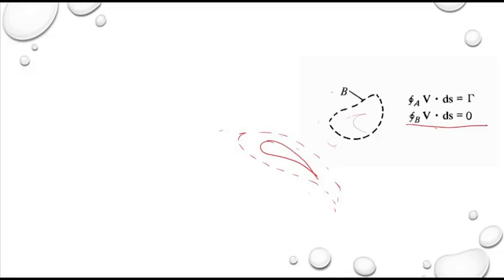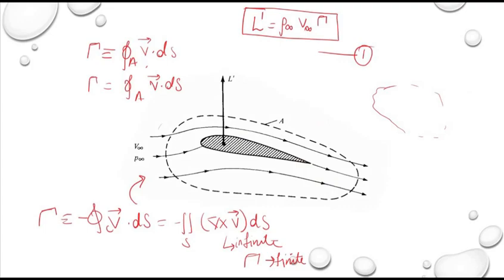Rather, the reason why we see lift on an airfoil is the net imbalance of surface pressure distribution, and circulation. So these are the two reasons. You cannot just mention circulation. So how do we relate this? Equation 1 gives the relation between the surface pressure distribution, which is producing lift per unit span, and